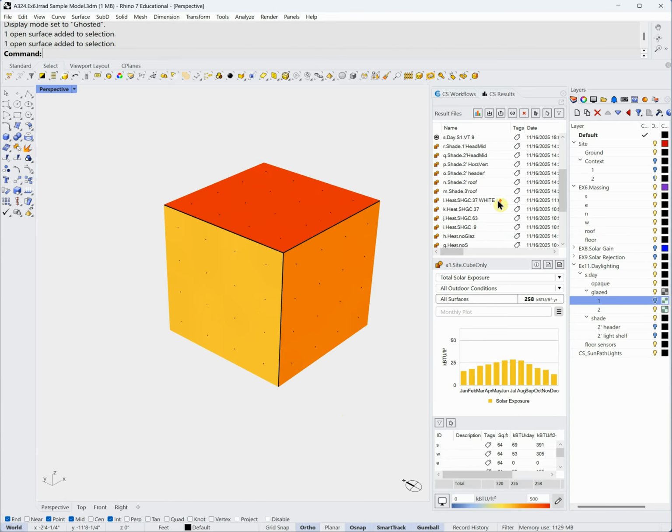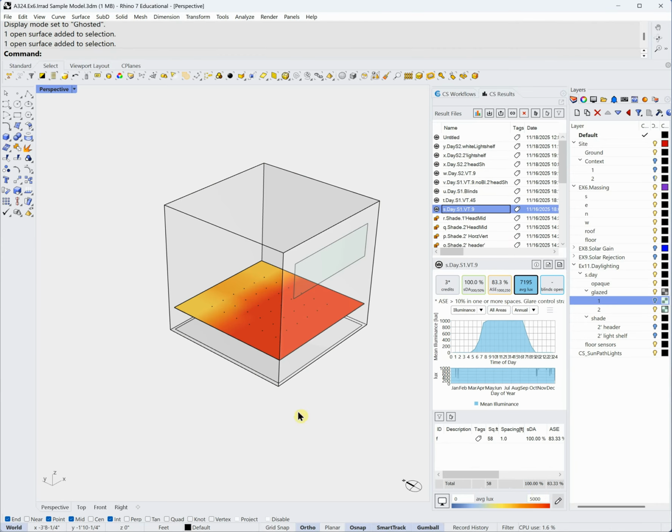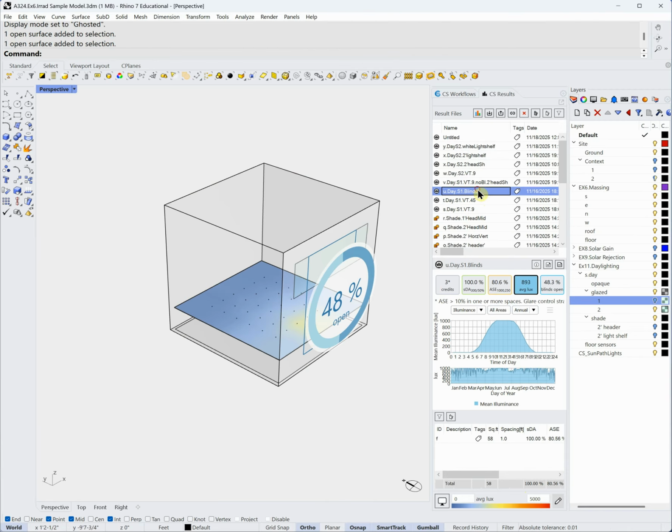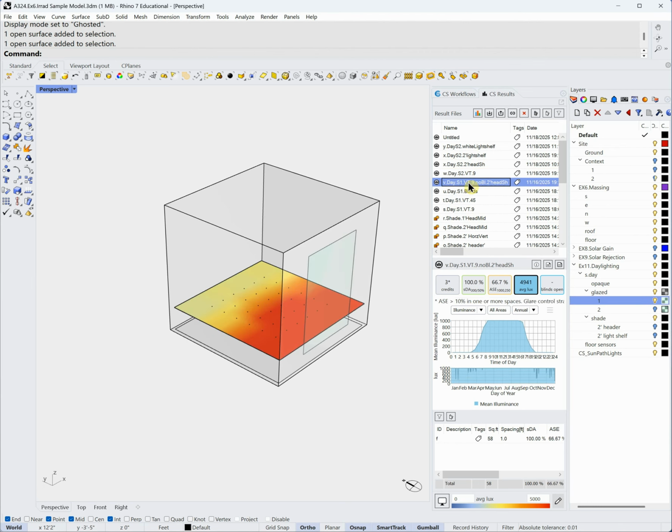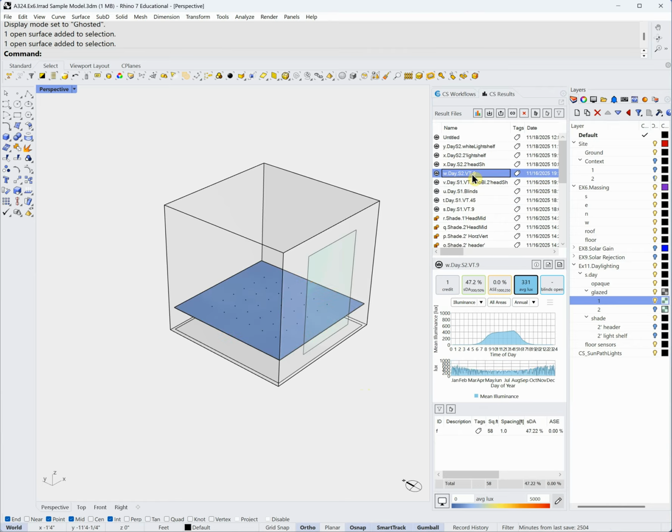So I'm going to now go back to my simulation and make the point again that when I first ran it, I had this set at 5,000, and that made sense for the initial runs, when I had the large glass, when I had this glazing set up, so up to here. And then what I'm saying is that when I got into this, since it was so drastically different when I switched to the second glazing setup, I changed to 500. Now I could set this to be 300 to 500 if I wanted it to be just within the range.